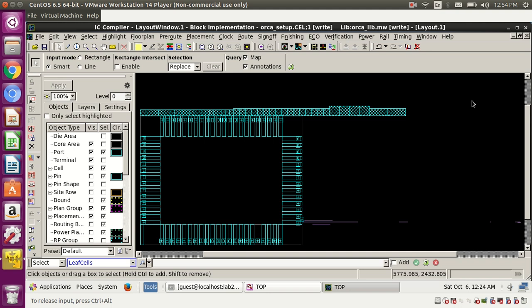So when we have a design with 10 or 11 metal layers, horizontal and vertical give more routing resources, more tracks. That is the most optimistic one. That's why we give it. If we give vertical or diagonal, then one more issue comes.